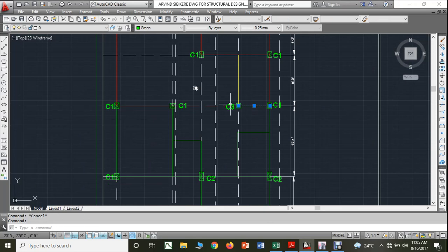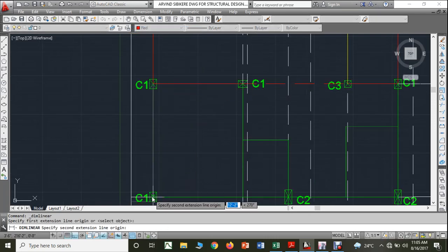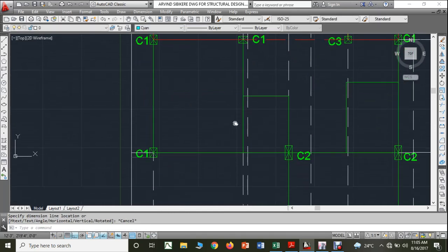Even this I have already done, right? So then this and this will come. What is the dimension? This I have to take as continuous only, that is 12 feet 2 inches. I will make it 13 feet, but this again I won't consider as a continuous beam.